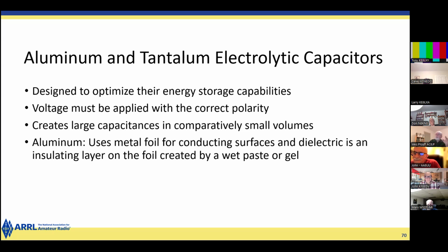What happens is when the input voltage is higher, the capacitor stores energy, and when the input voltage is lower, the capacitor discharges energy. We'll go through the detail of that in a later section, but the idea is you want a large amount of capacitance so it can store a large amount of energy. At the same time, you want all that energy storage in as small a volume as possible so that your radio doesn't grow too big.